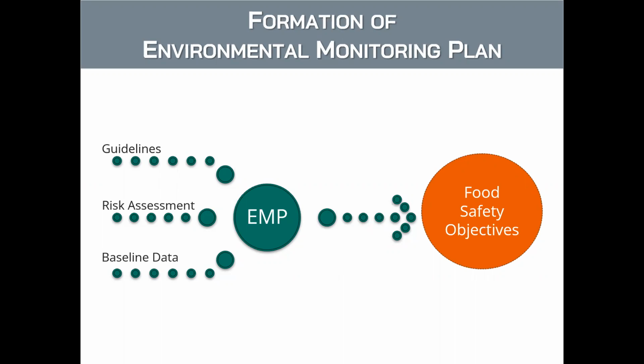Thirdly, it is advised that you collect baseline data to demonstrate the microbial burden in your production facility and help you with risk assessment. Instead of speculating, you can just perform some sampling, send the samples to the lab, and obtain some background or baseline data.